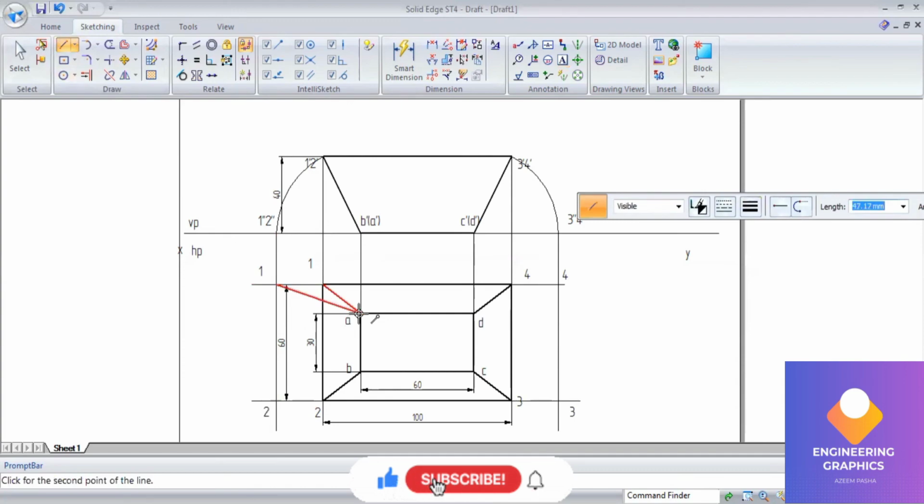Now you can connect with a straight line from 1 to A, from 2 to B, and from D to 4 and C to 3. That's the development of that particular portion. Now we have to cut the arc of this length, 1A on the right side and D4 on the upper side and B2 on the lower side and C3 on the lower side. You can connect it. So this is the development of this particular portion of this side.